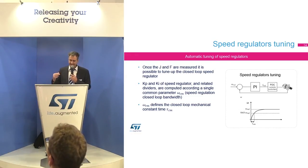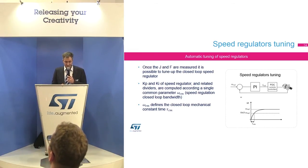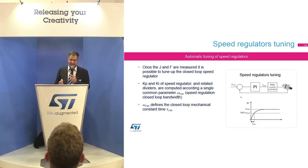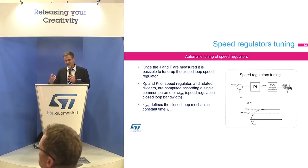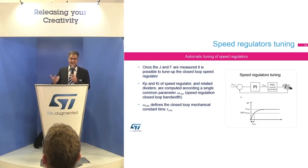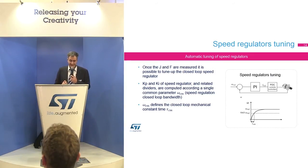So we have the speed regulation algorithm. We have measured the inertia of the motor and the frictional coefficient, and then we can set up automatically the proportional and integral terms of the speed regulator starting with a single input parameter, that is the bandwidth of the closed loop system.